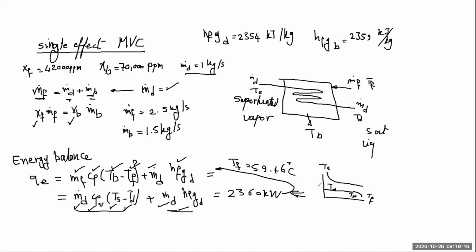And the lower line is the one that has been considered by that expression here. In that expression, T feed is not given, and we get it from this kind of balance. First, we calculate how much is the heat transfer rate in the evaporator, and the rest is to make use of it to calculate the feed temperature.